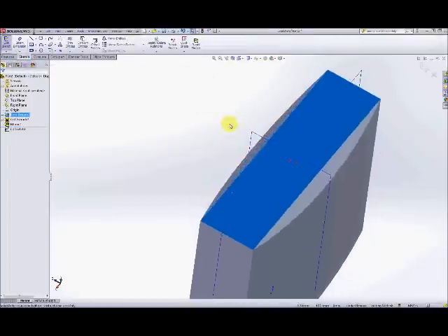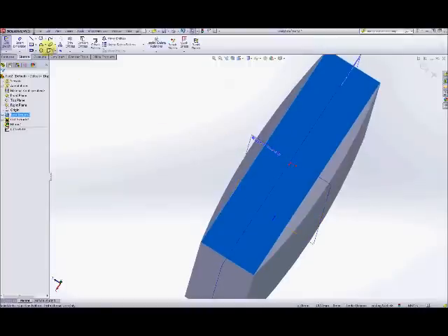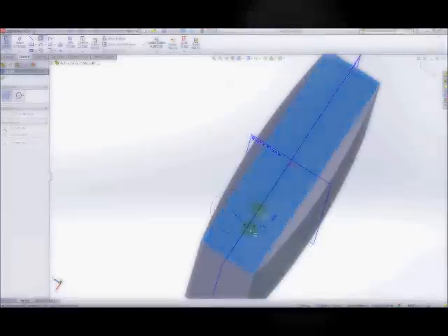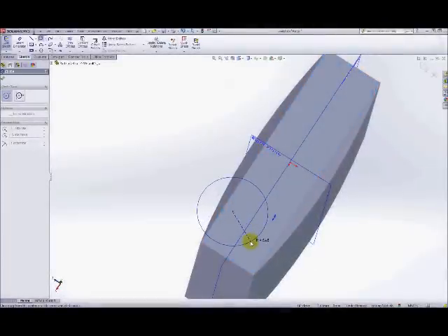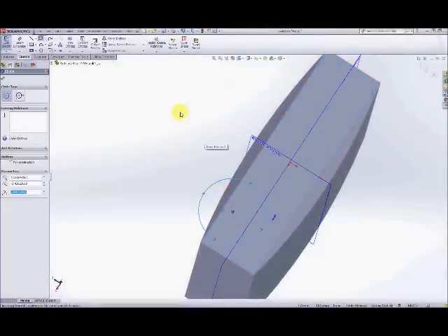Now these holes are going to be just circular holes bored into the padlock body. So we're just going to use a circle command. We're going to use the center circle without much concern about where it's placed or how big it is, which is a typical process in SolidWorks.